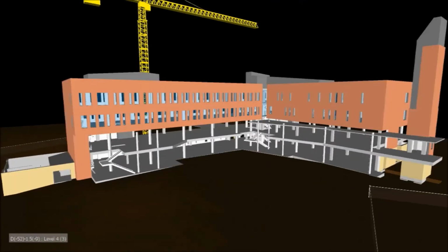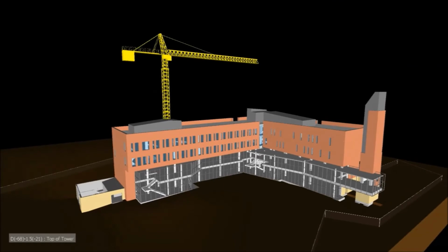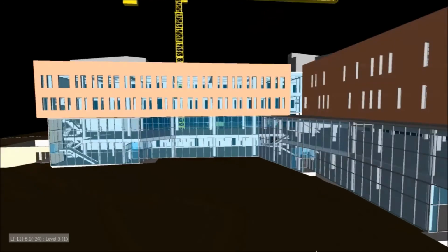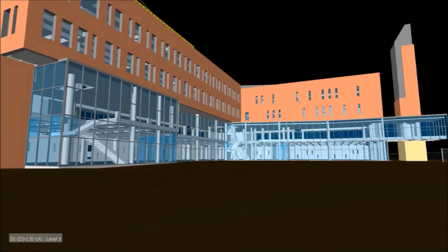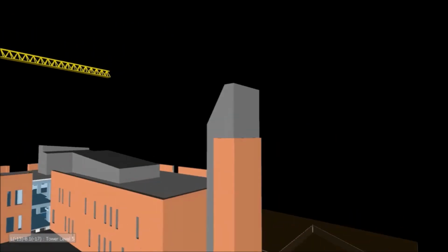The mullions for the curtain wall system will then be installed, followed by the remaining roofs. Next, the glazing for the curtain wall system will be placed, followed by the exterior doors. Finally, the soffits will be installed to complete the building drying process. Blocks will be placed prior to the crane being taken down.